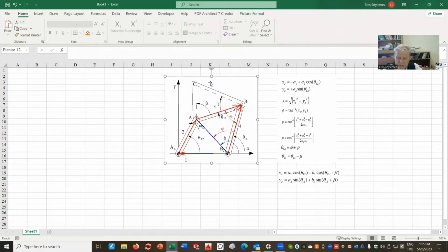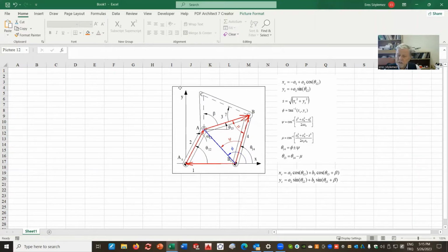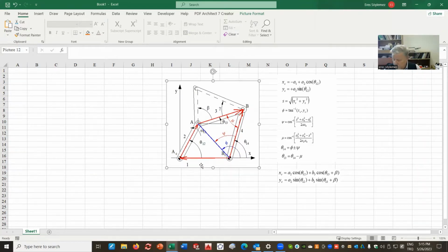we are given all the necessary link lengths for the analysis. In case of synthesis, we are going to determine those link lengths. But whenever you are given those link lengths, we form a quadrilateral. But you don't know exactly how this quadrilateral is because in case of a quadrilateral, this four-sided figure can collapse, can be at any position. So this mechanism is going to have 1 degree of freedom in that case. So we have to define one of the angles.